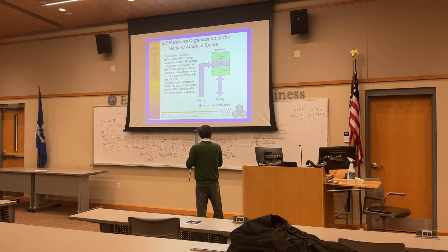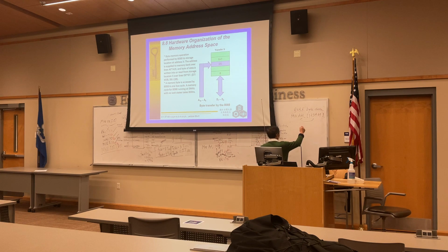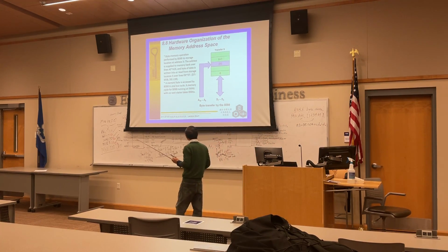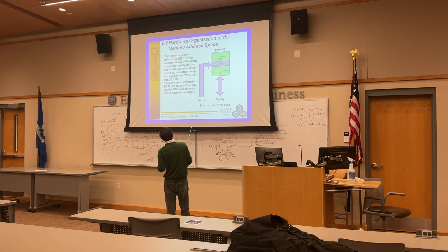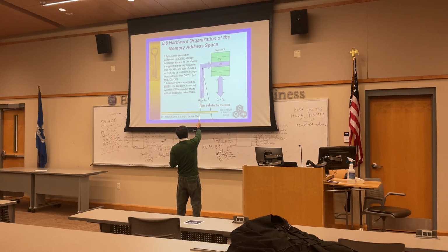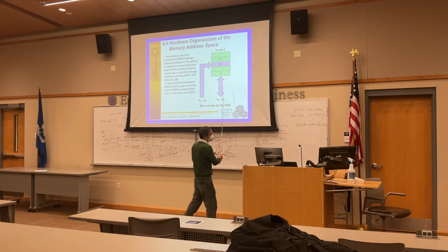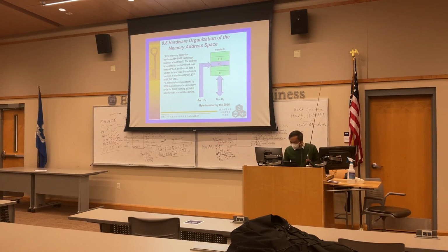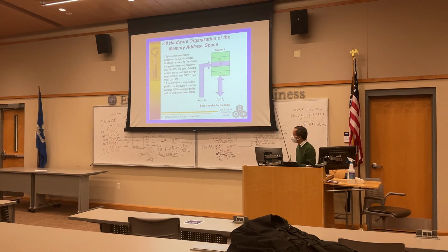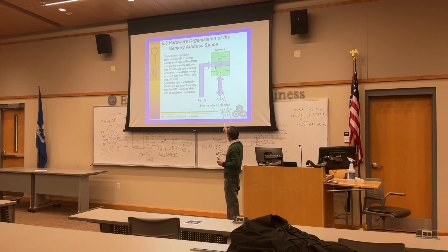First, the microprocessor is going to calculate DS times 10H plus 1234H. That's the physical address, A19 to A0. This physical address is going to be broadcast along the address bus. Then we locate this data and send it out to the data bus.